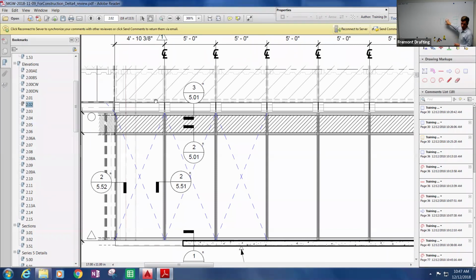This happens with precast or GFRC, typically the heavier, more monolithic elements on a building. Windows are pretty flexible. Aluminum, with a little joinery and things like that, they bend a lot. But precast and GFRC tend to be heavy masses of stuff, and there's not a lot of flex in them, so they just move horizontally left to right in seismic.